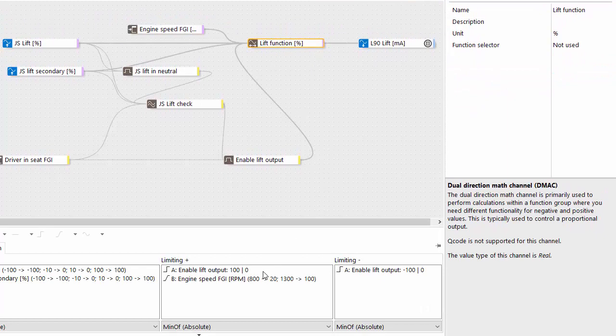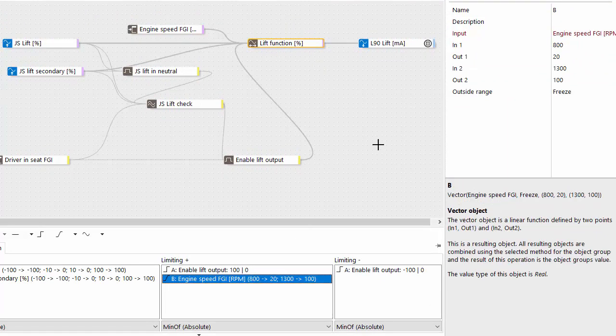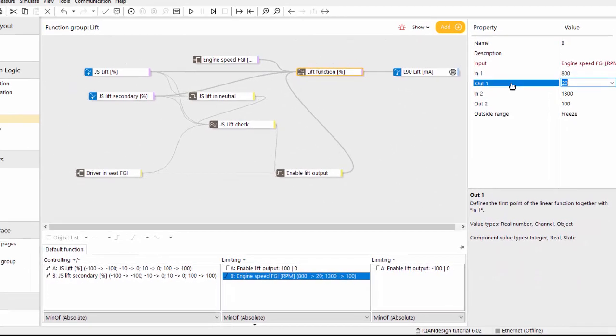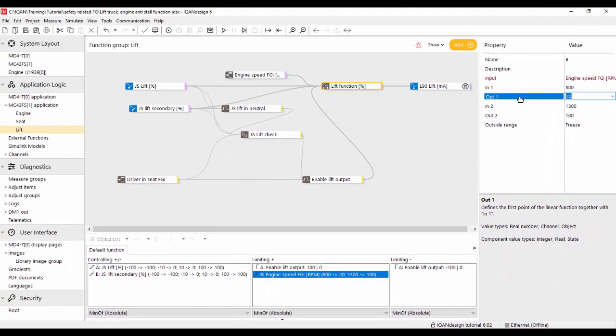And I mean, that's one thing that we can't get help with from the project check: looking at how the logic actually works. So here it's built so that it's a limitation that only changes the speed limitation. It doesn't put it to 0, and that's an important part. It doesn't mess with the restart conditions or anything.